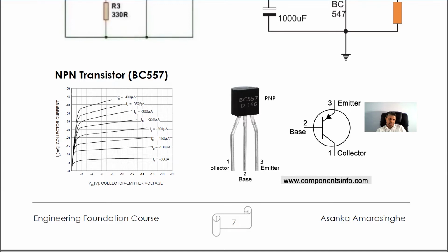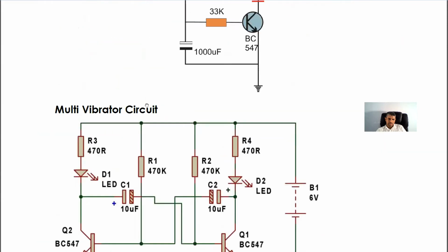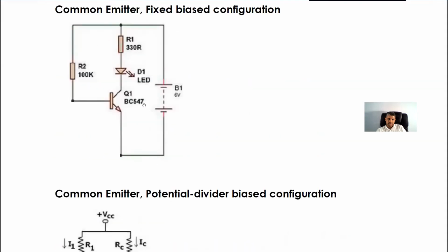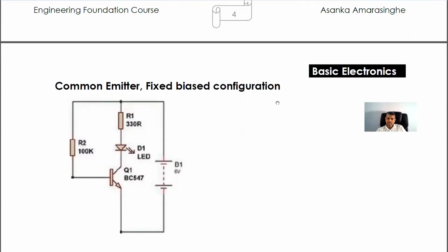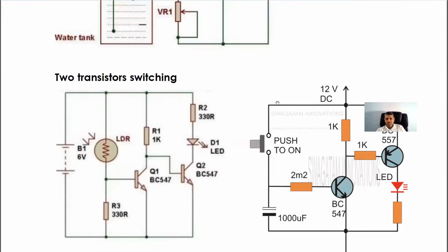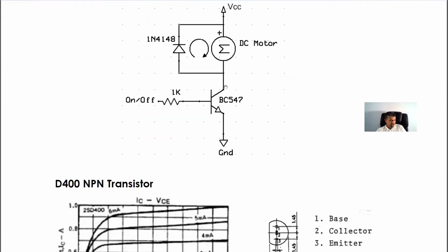In the characteristic curve of BC547 that we discussed on an earlier day, you see only microamperes. DC motors consume more than micro, they will consume milliamps. Therefore, it is not sufficient to use BC547. If you want, you can use BC547 and test this circuit.